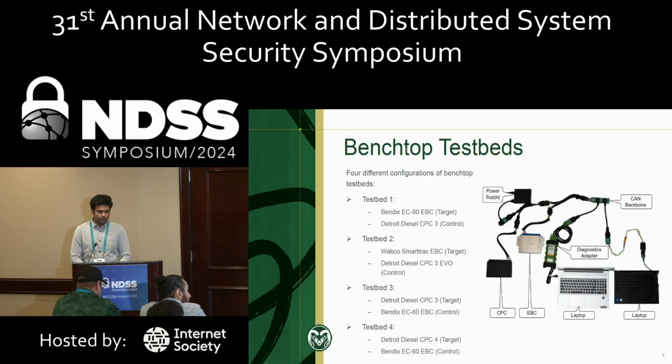We did our experiments on both benchtop and experimental vehicles. We had 4 configurations of benchtop ECUs configured, as you can see in the diagram over there. We had a laptop which acted as our diagnostic tester. We had a laptop from where we performed attacks. They were all connected through a CAN backbone, and 2 different configurations of ECUs for 4 different test benches. And we did test all our attacks out on multiple different configurations of ECUs. And in each configuration, one was a target, the other one was a control ECU. So one was subject to attack while the other was not.